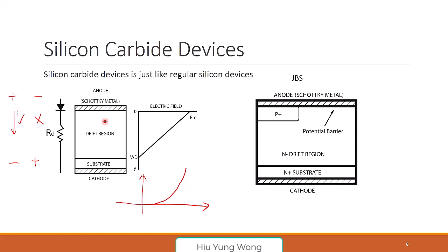When I have a drift region, I'm going to have a lot of resistance, right? So why don't I reduce it? When I reduce it, what happens? Can you say again? The breakdown voltage would decrease. The breakdown voltage will decrease. In our class, it's always on-current, on-resistance versus breakdown. Just now you mentioned capacitance is also important. That's related to loss also, right? So capacitance is indeed important. But here we just say, why do I want to make it so thick?